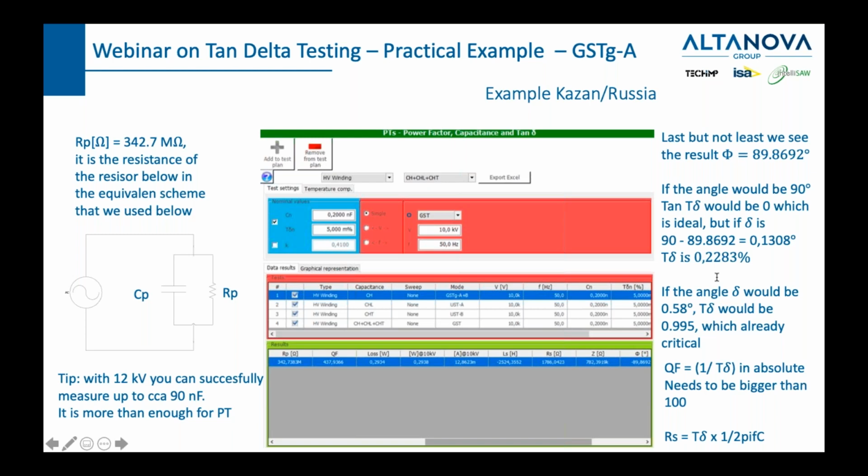The current passing through a surge arrester shouldn't be too high when the nominal voltage is on the line. So you would do the same thing. You would generate your voltage on a surge arrester, and you would need to have either previous values or a table, or talk to the producer of a certain surge arrester to understand what the nominal power consumption of your surge arrester is in order to be sure.